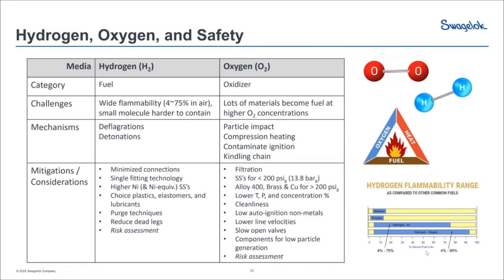System line velocities and limitations thereof may drive tubing sizing increases. Certainly component layout, what components to include, and specific component features can be driven by the molecule that we're carrying. And also, operating processes to complement these systems is paramount. Think things like purging operations for hydrogen or proper preventative maintenance for oxygen, where the goal is to both preserve cleanliness as well as avoid those ignition mechanisms.